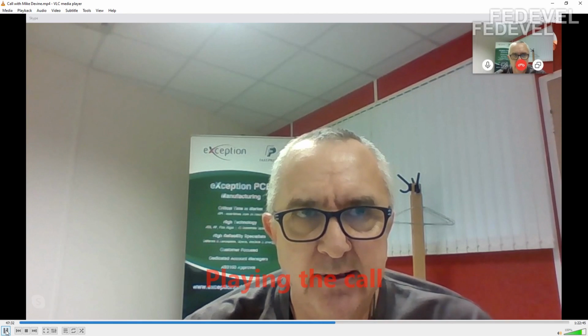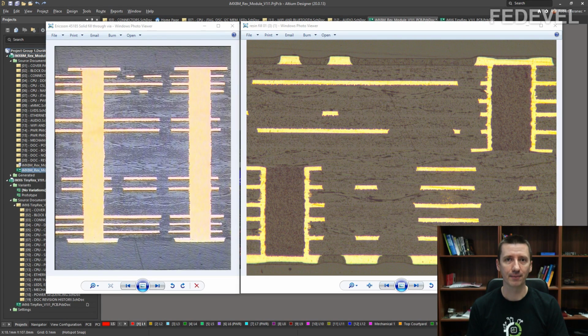Okay. In the next clip, I wanted to know if there is a difference in quality of the pad between using copper filled vias in pad and resin filled and overplated vias in pad. And as you can see even from this picture, there actually is some difference in quality of the pad. But watch the next clip.